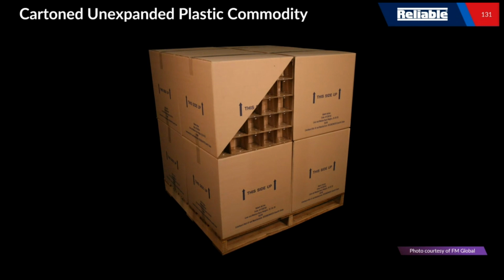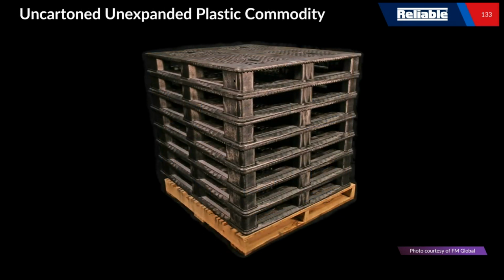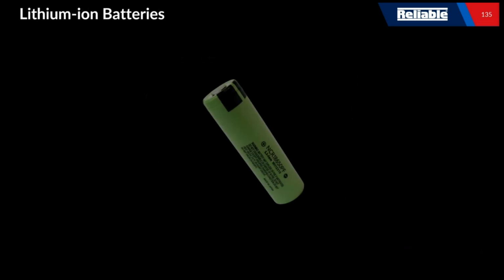If you run a test and pass it, you get a listing for that hazard. We've seen those hazards all throughout NFPA and FM. But the one thing you never see is a listing for batteries. So batteries are the challenge. There has been no standard commodity test identified that we can go to UL or FM, pack the racks with, and then get a listing.